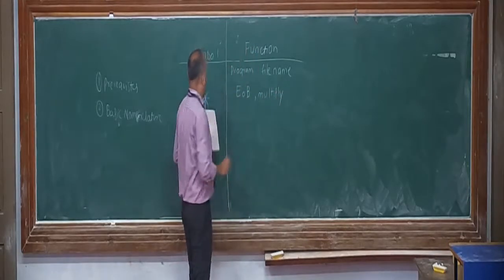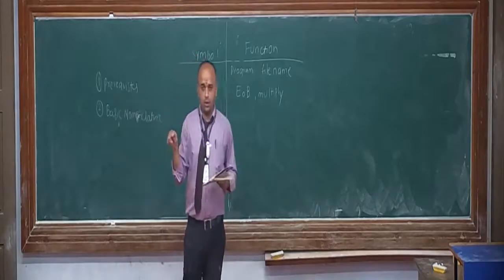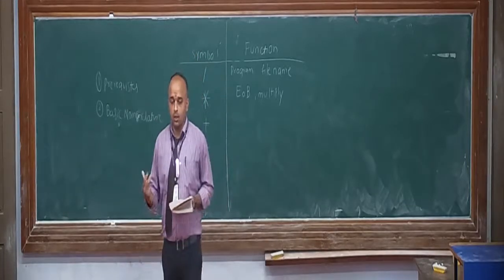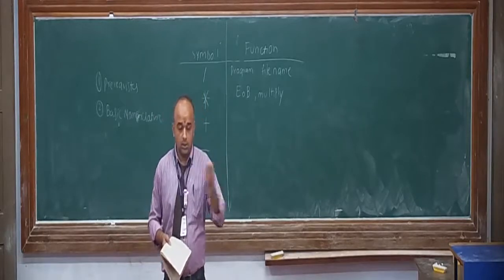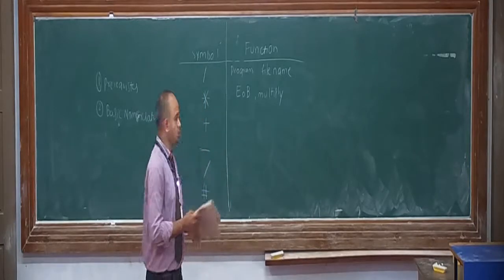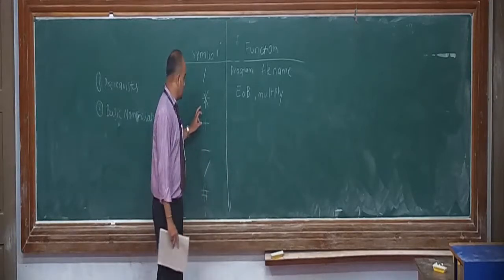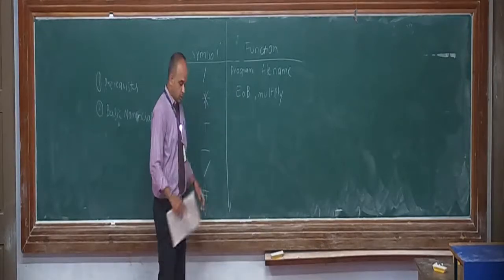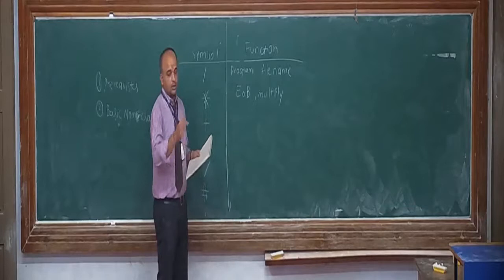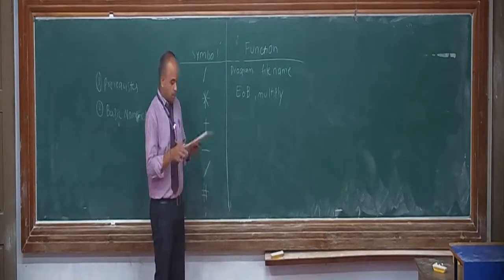Now, even in the alphabets there was a notation of end of block. What do you mean by end of block? Suppose a line is over and I want to go to the next line; how should the program or the computer understand that? So we put a standard notation like this asterisk sign, and also the colon, which tell that it is the end of block. It means the line is finished, so the cursor has to go to the next line, and the next line has to be executed.